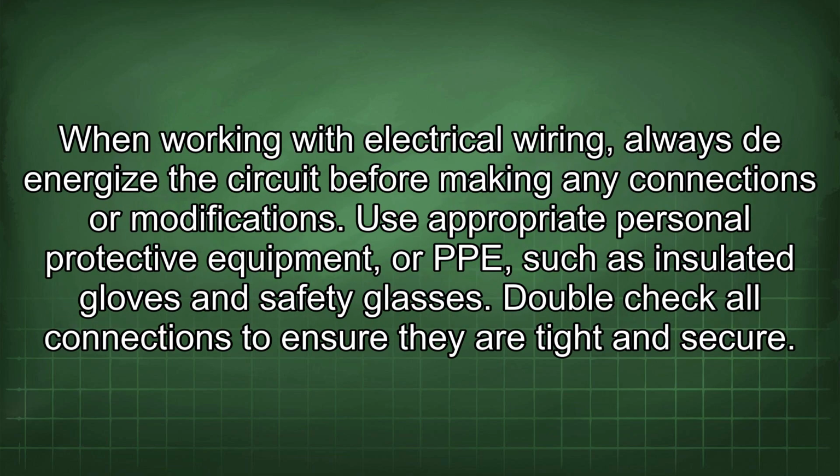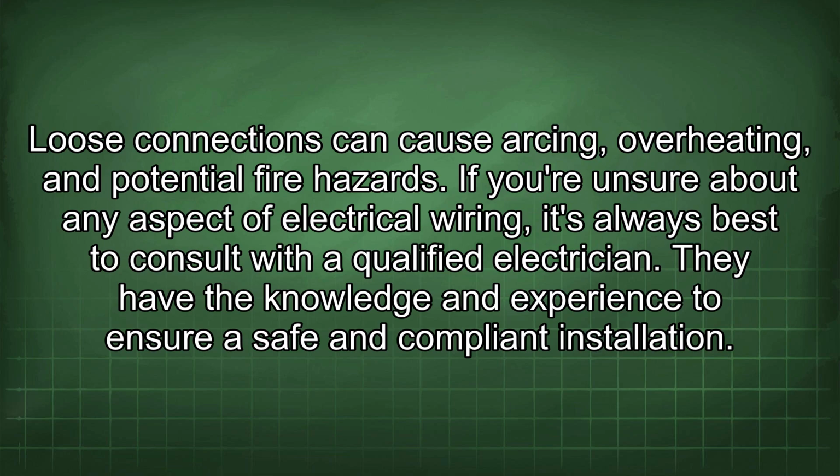When working with electrical wiring, always de-energize the circuit before making any connections or modifications. Use appropriate personal protective equipment, or PPE, such as insulated gloves and safety glasses. Double-check all connections to ensure they are tight and secure. Loose connections can cause arcing, overheating, and potential fire hazard. If you're unsure about any aspect of electrical wiring, it's always best to consult with a qualified electrician. They have the knowledge and experience to ensure a safe and compliant installation.